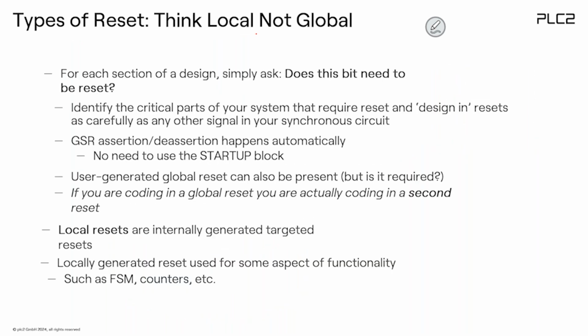So always ask yourself, do I really need to reset? Do I really need to spend the reset signal to clear this bit? Maybe we don't need an asynchronous reset, or maybe you don't need a reset at all.